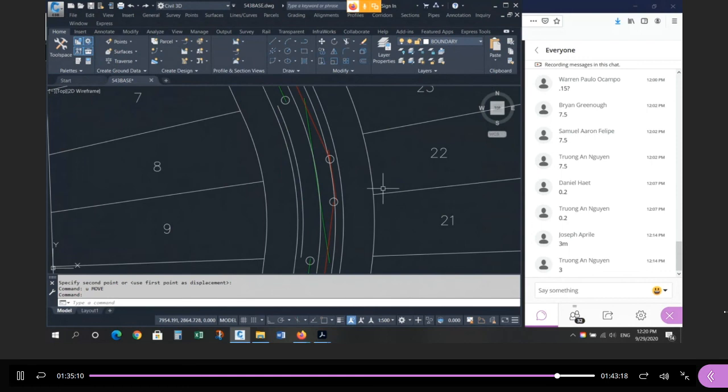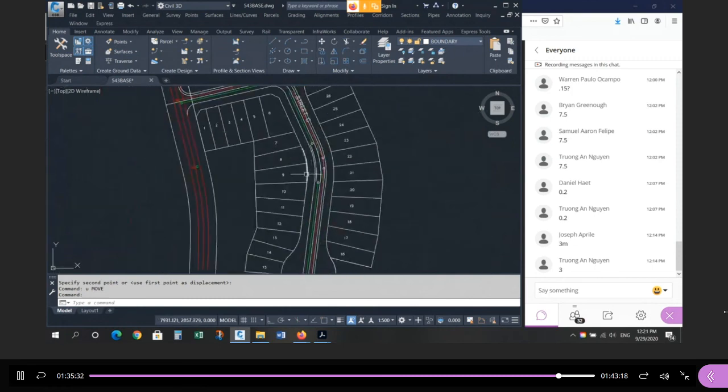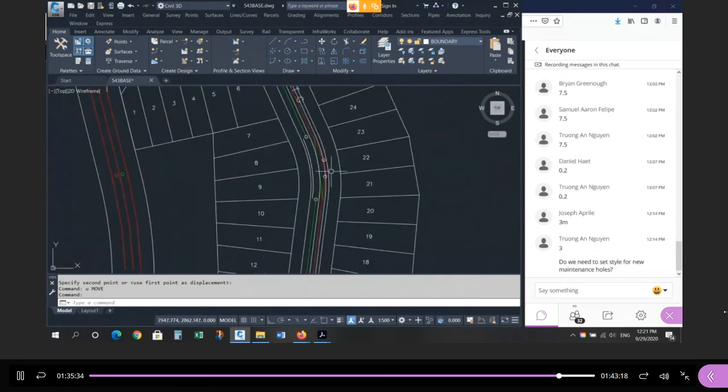And I'm going to look for that when you lay out your pipes. And you can see there's an infinite number of places you can put them. What I'm looking for is the structure is at least 1.5 meters away from the pavement edge, the pipe is at least 1 meter away from the pavement edge, and that the pipes are parallel and 3 meters apart. That's in keeping with the spirit of the standard. So, you know, when you navigate turns, you have to do that.